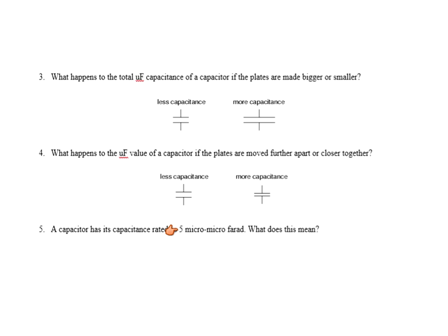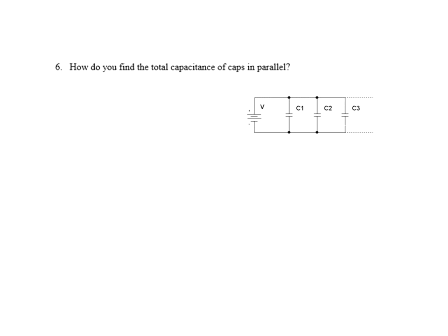So in case you run into that, a capacitor that's rated in 5 micromicrofarads typically would mean that it's 5 picofarads. I haven't seen that one for a while, but you just never know. You never know when you're going to see that. That's kind of an odd one that appears every once in a while.